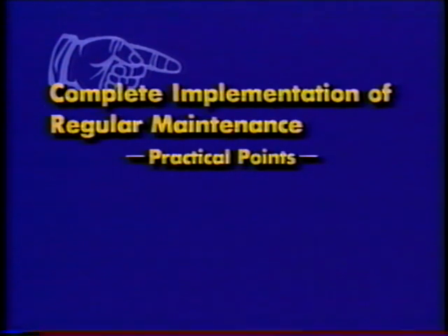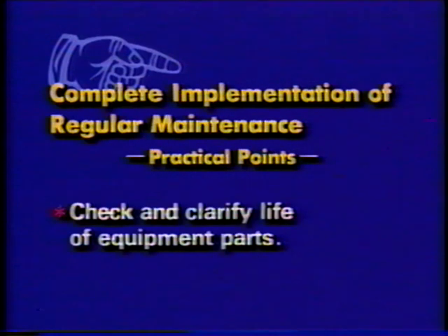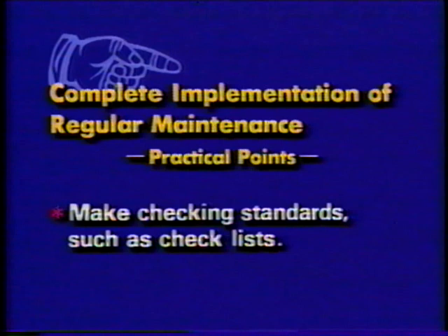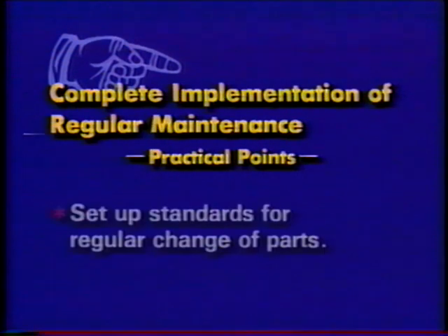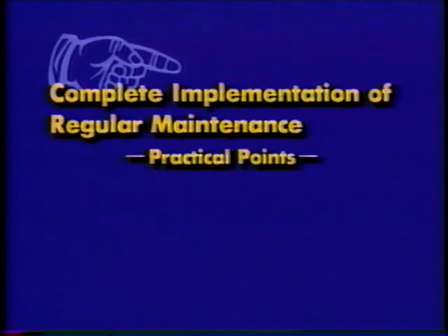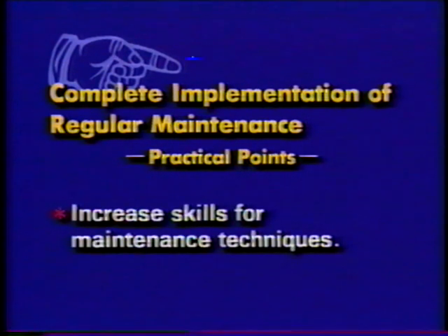Here are the main practical points for complete implementation of regular maintenance. Check and clarify life of equipment parts. Make checking standards, such as checklists. Set up standards for regular change of parts. Increase skills for maintenance techniques.